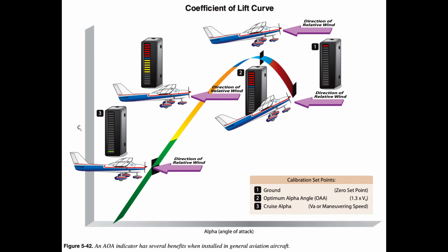Additionally, the less energy that is utilized to maintain flight means greater overall efficiency of the airplane, which is typically realized in fuel savings. This equates to a lower operating cost to the pilot. Just as training is required for any system on an aircraft, AOA indicators have training considerations also. A more comprehensive understanding of AOA in general should be the goal of this training, along with the specific operating characteristics and limitations of the installed AOA indicator.